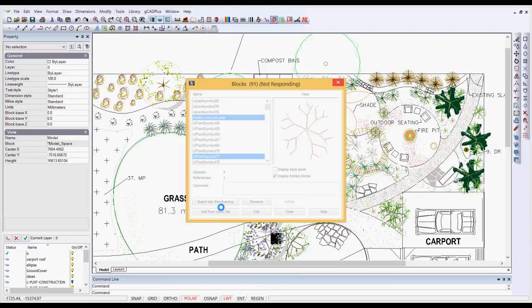So it's not a problem at the moment. We can't program our way around it. We can just alert you to the fact that if you use blocks with blocks inside the same name as the block, that circular reference can cause you grief. It will do the same if you happen to be using AutoCAD as well, but AutoCAD is likely to catch that and say you've got circular references. So we ask you to be a little bit alert to when you are creating blocks. Don't make a block of the same name inside your block.